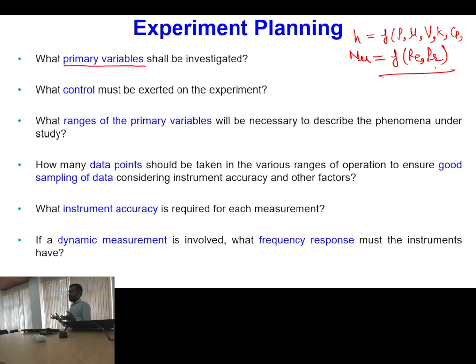So it means that if I have to calculate the heat transfer coefficient, obviously my aim will be to decrease the number of measurements, or decrease the number of parameters. Then I will present my results in dimensionless form, and moreover the dimensionless form gives a more generic nature to the results. So the Nusselt number I need to calculate is my output parameter, but the Reynolds number and Prandtl number are input parameters.